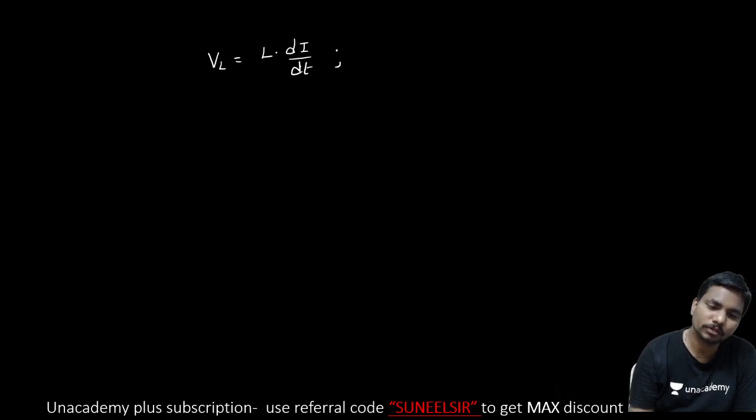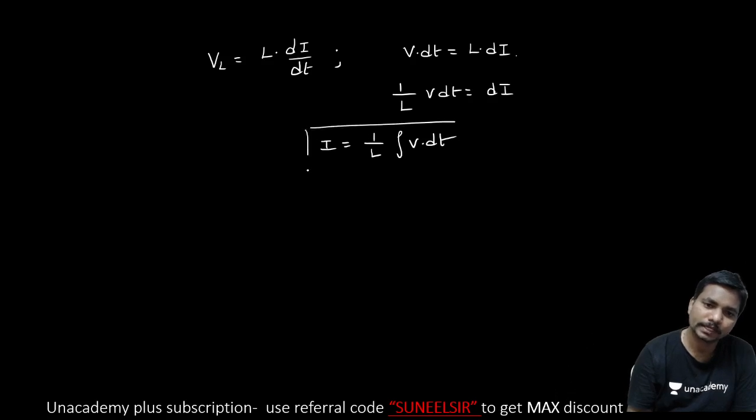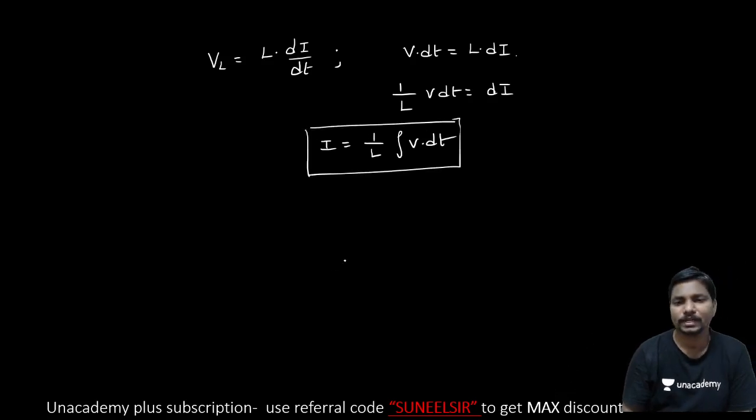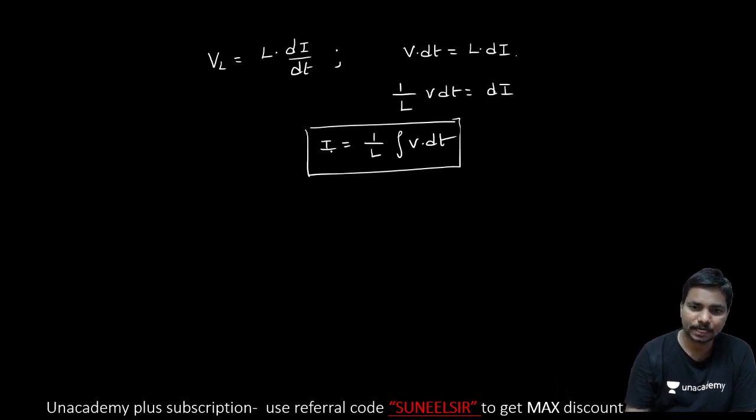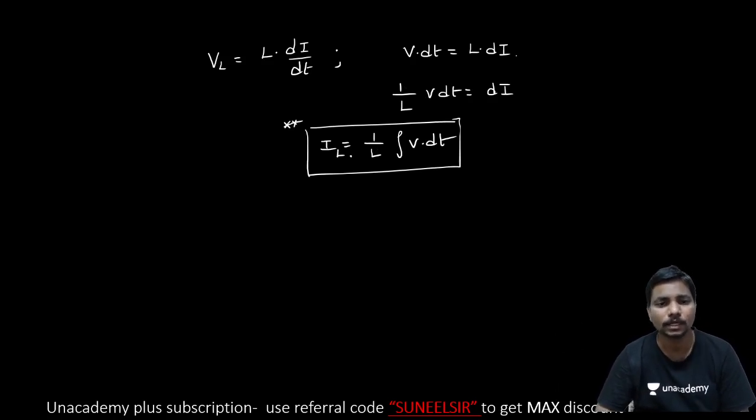From this, if you want to find the current, then V dt is equal to L into di, so 1 by L V dt is equal to di. If you integrate this, you will get current I. Current I is equal to 1 by L integral V dt. So you got the current through the inductor.